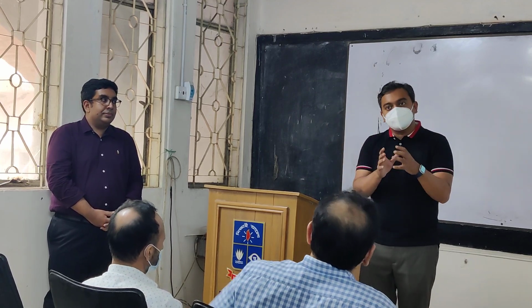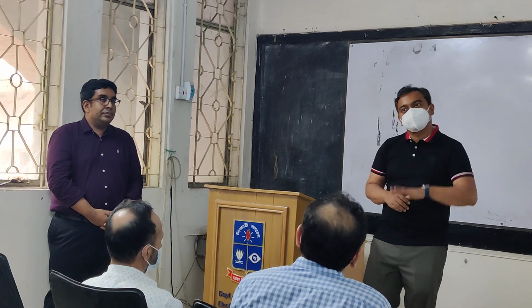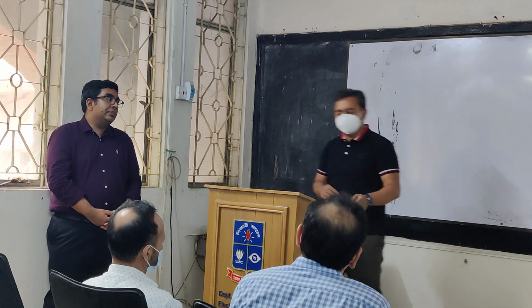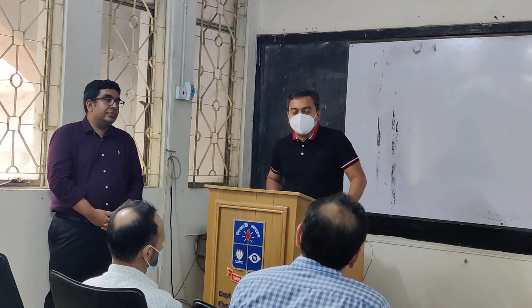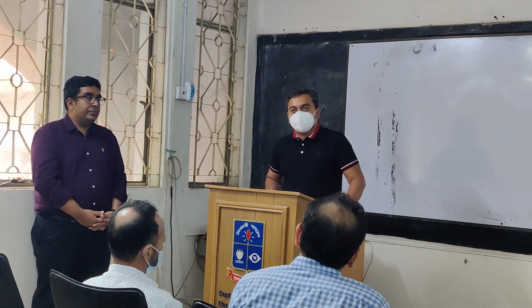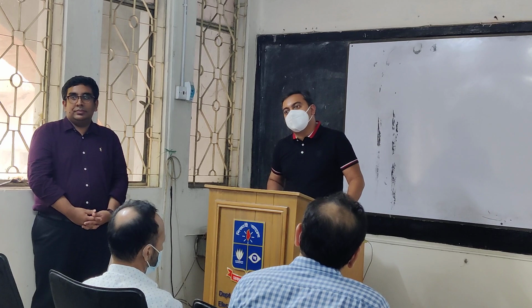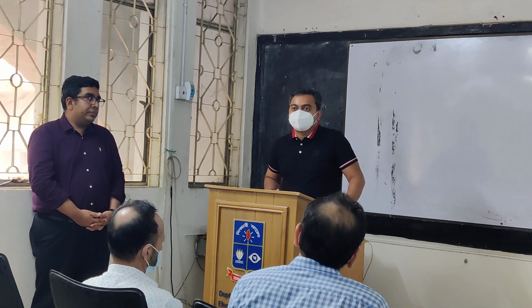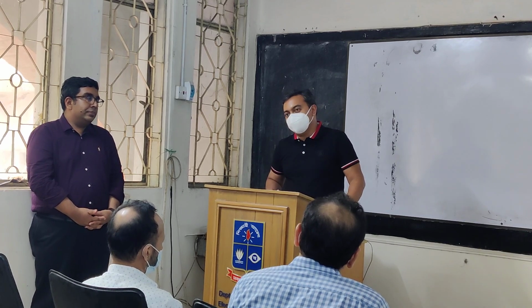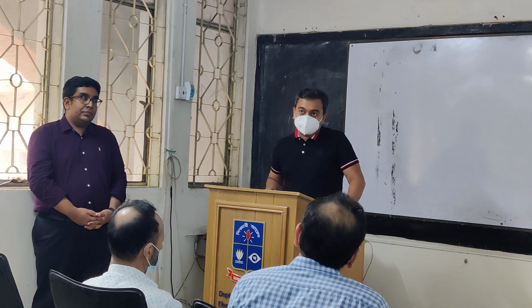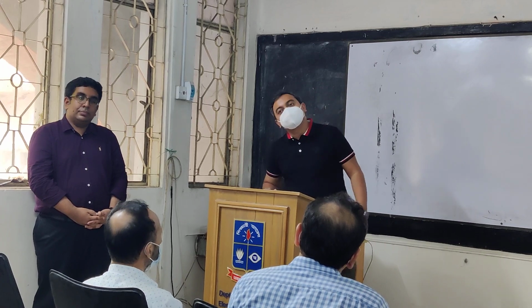So you take an average, it comes out around 1 femtojoule per bit. So from that point of view, 10x to 100x is my personal target in the short run. What that amounts to is running a transistor at 350 millivolts. Today, transistors are running around 1 volt. But if you can reduce the voltage by 3x, then your dissipation goes down by V squared, which is 9 times.